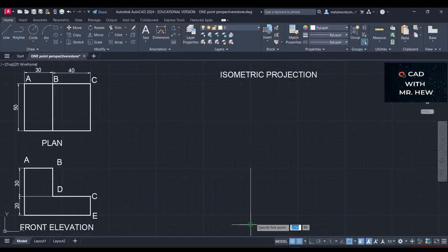Right, so we're gonna start off with the drawing here. Can you guess what the angle would be for isometric projection? It would be 30 degrees to the horizontal, right? So if you were using a T-square, you would use a T-square and a 30/60 set square, which would be the taller one of the pair, all right? Looking at the drawing, you can turn the drawing different ways, depending on how the person wants to look at it. But I'm gonna be using C E as the lowest point, and you'll see in a little while, right? So I'm gonna draw the baseline, which should be 50 millimeters.